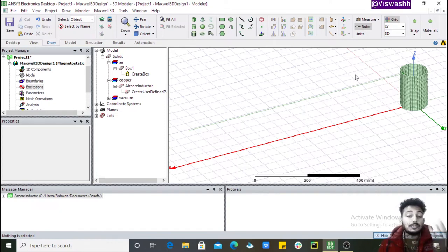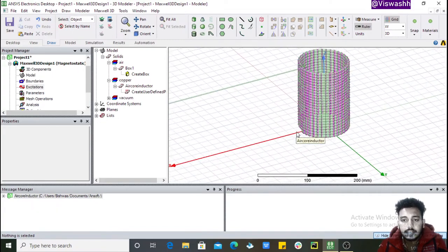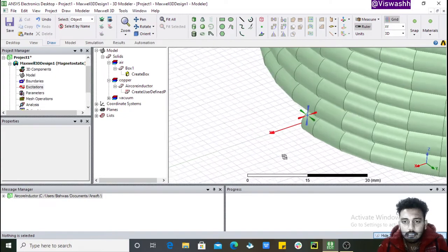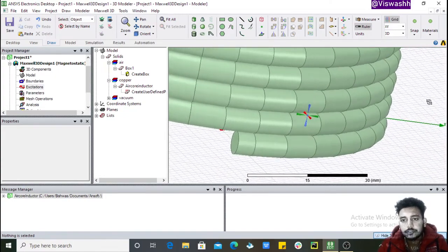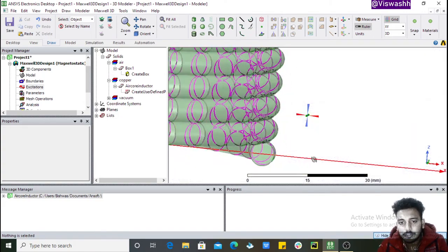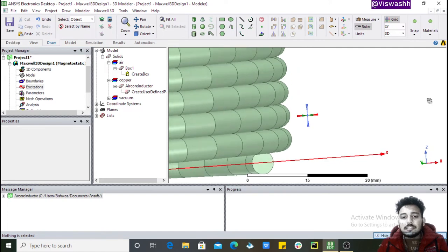Now what we'll do is we'll subtract this lead later on to the surface and just attach the surface with the lead. That we'll do later on, but for now we need to drop another lead right here using the same process, exact process. Now the lead in the terminal is on another side, so I will use again the rotate feature by pressing the scroll button in the middle and I will rotate it. That's the easiest way to do. So slowly I will manage. Again I will rotate from this side, again I will rotate from this way and from the sides.